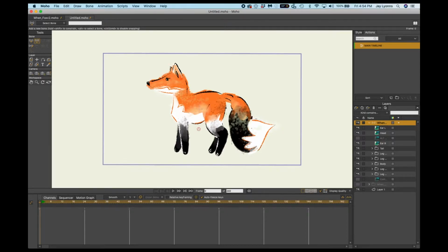This will be a control bone, so I'll position it somewhere underneath my character so that it's not confusing with the other bones. It'll be much larger than the other bones as well, so choose the best place to locate your control bone. Click to start creating the bone, and drag to resize it. If you hold down the Shift key, it will constrain the angle of the bone by 90 and 45 degrees. We'll bring it straight down 90 degrees for this character, and this will be my character's controller.